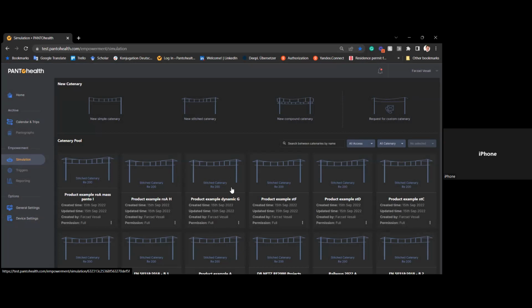That's right, because we usually hog the section insulator a little bit, as the pan pressure comes to the section insulator, to make it all nice and smooth. So that hogging of the section insulator sometimes is quite critical, and you have to know exactly how much to hog the section insulator to get a smooth run with a pantograph. Yeah, definitely.